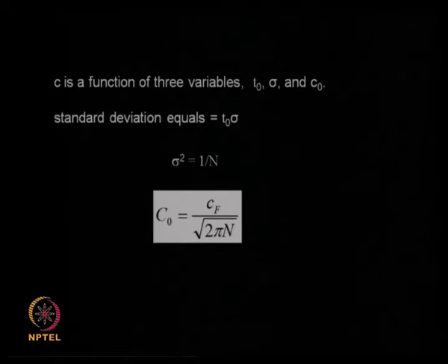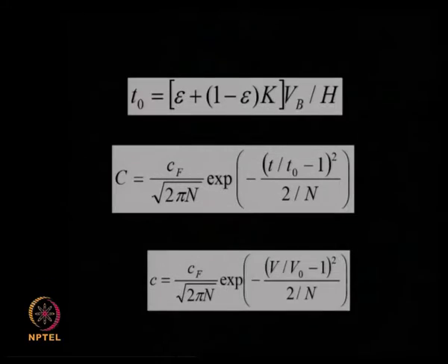We are going to look at it as time progresses. And then T naught, that is the elution time, the time at which the peak is maximum, is related to your voidage, your linear adsorption isotherm term K, volume of the bed and height of the bed, in this fashion.